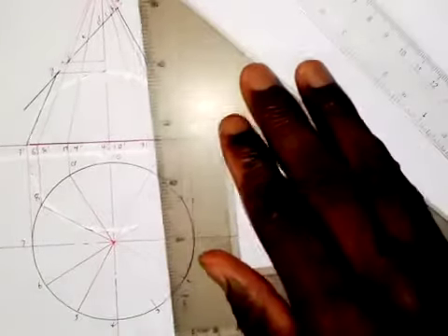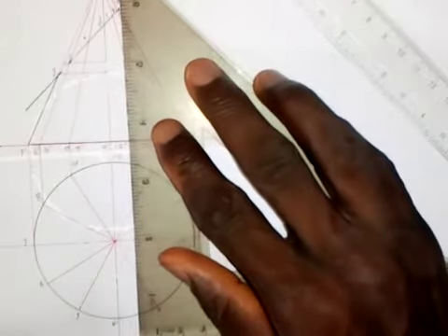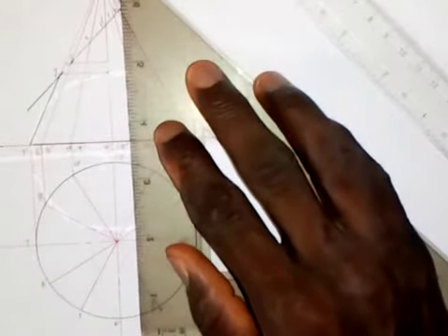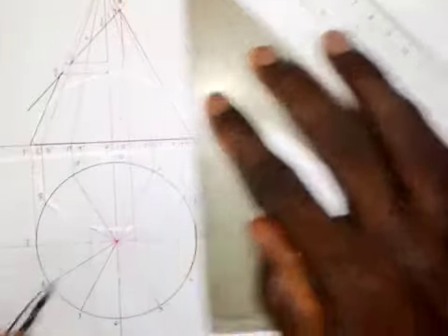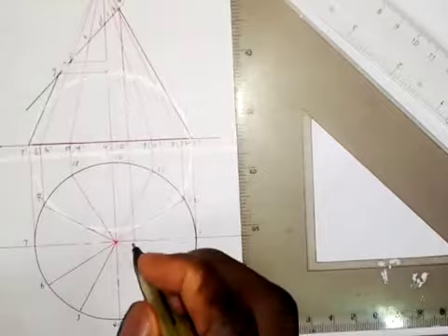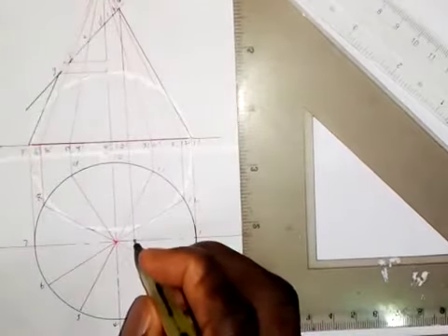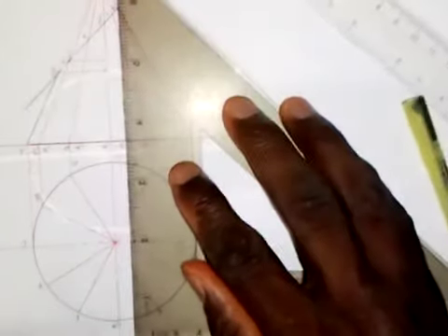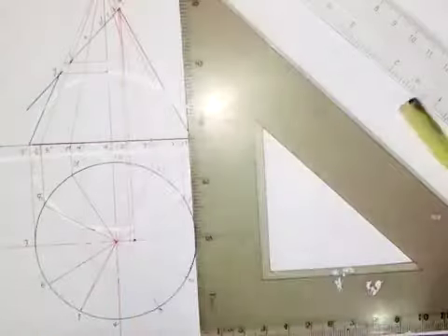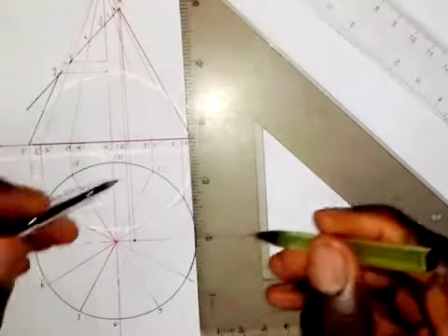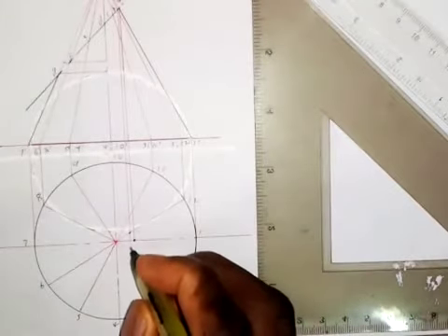All right, so from this point A here, I'm going to draw a vertical line into the plan for us to have a complete plan. That's why we are doing this. So draw a vertical line. Wherever this vertical line touches this line 1, we take note of it. So we have this point. Then from point B, draw a vertical line like this. This line contains 2 and 12. So it touches 12 here and it touches 2 here.